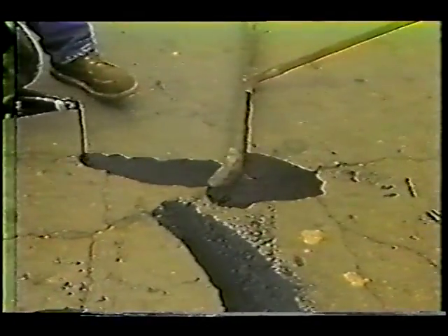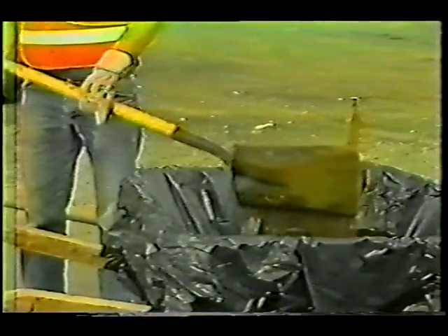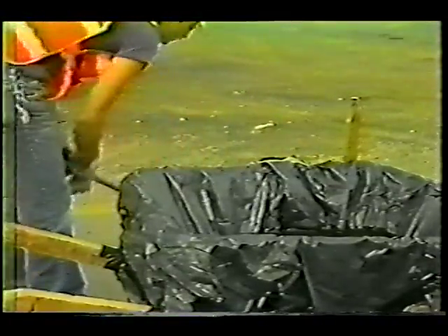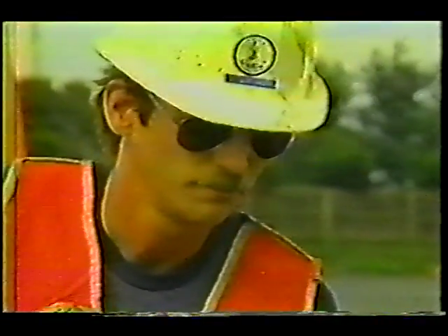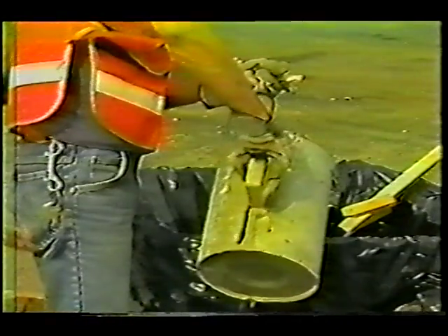The proper equipment alone will not make a good repair. You will also need the proper materials, which include an asphalt slurry mixture for filling the cracks. This mixture can be made before you go to the work site. It consists of 10 liters of asphalt emulsion to every 35 kilograms of sand, with water added as needed. The mixture has reached the desired consistency when it is thick, smooth, and free of lumps.